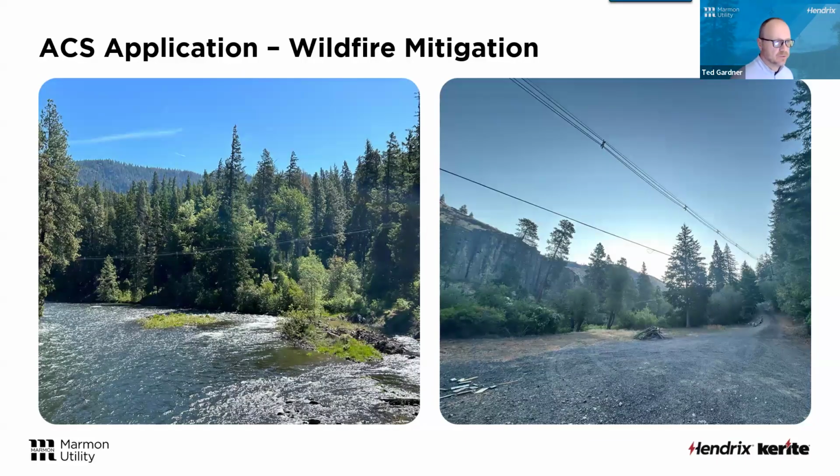The one on the left here shows one of our longer spans. Like I said, one of the key benefits for spacer cable is that to do a longer span, we're focused in again on the messenger. We don't have to increase the size of the phase conductors for those span lengths. Whereas if you do bare wire or even tree wire, that cable has to support the tension for that span.